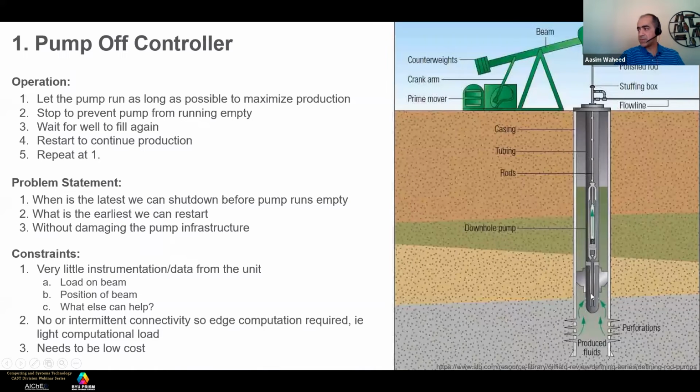And this is what they're doing. Again, the pump itself is actually many thousand feet down the well. It's another completely off-scale picture, but that's the pump itself, and this beam is actually running this pump. What the pump is doing is taking oil from the well and pushing it up. The way this works is that as it goes up and down, it takes liquid from under this valve on each downstroke of the beam and pushes it up on each upstroke. And that's how oil flows up.